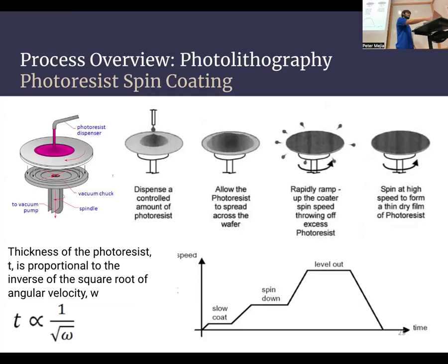Pipettes. Yeah, so you're going to bring a pipette of your photoresist and put it on the wafer. There's a general guideline of how much to put on so that you get enough. If you put a little extra, it's not a huge deal. You're going to lose some anyway because it's spinning, and you have a bunch of surrounding area that you'll cover with aluminum foil so that it doesn't get everywhere.